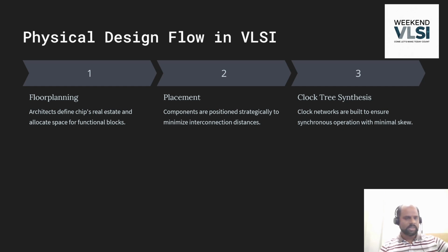Maybe it is entering from the other partition, or this block has a PLL. From that PLL to your leaf pins, the registers or memories, you should have the clock coming with certain latencies. Okay, that is why we build those clock tree structures. Okay, latencies are nothing but delays.